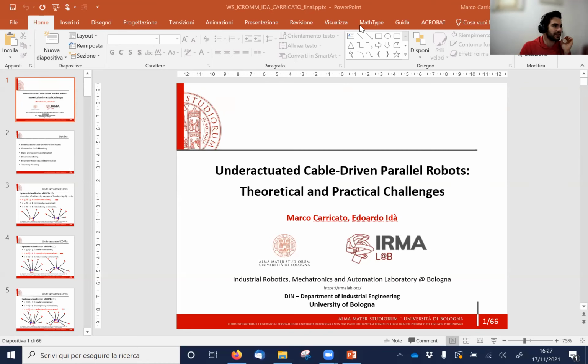If I can answer your question about integration, basically we are looking for a commercial solution which would allow us to have a high sampling rate with a high accuracy of especially orientation angles. So we are looking at industrial dynamic inclinometers or even tactical grade ones. Depending on the need for accuracy, you can choose either of the two options. For example, industrial may have a good enough accuracy if you just need to damp oscillation. If you really need fine control, probably the tactical series.